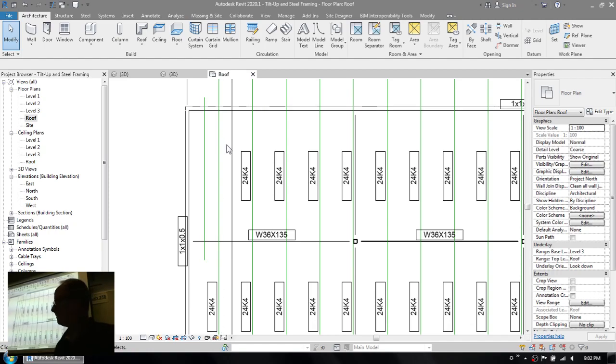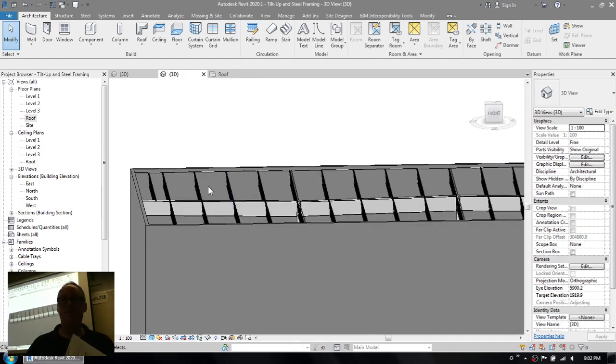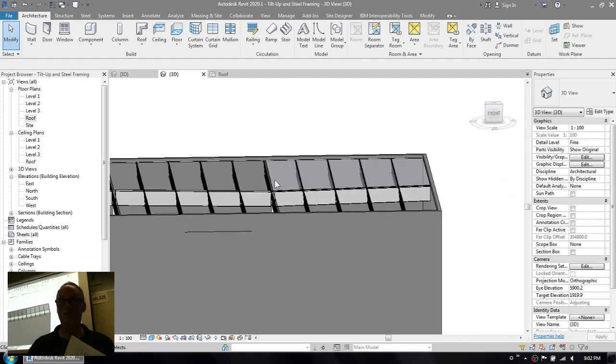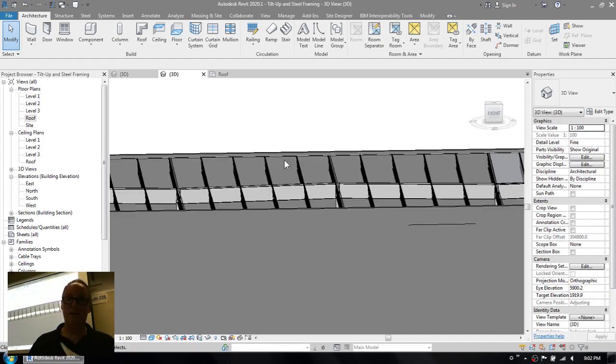And so unfortunately, with these sloping structure projects, you end up having to model each one of those joists individually if you really want to be accurate with how the structure is being modeled on the roof. I think on some projects this wouldn't matter. There's other projects where it would. So I had a project where there was coordination and there was limited ceiling heights, and I was like, screw it, I'm just going to model it. But if there's reason to do so, go ahead and go for it.